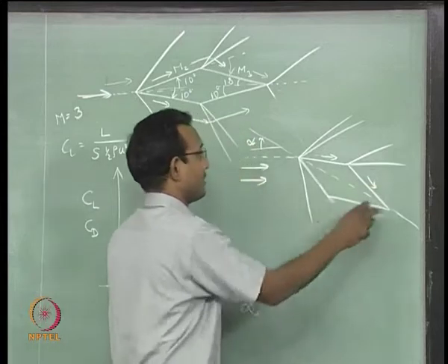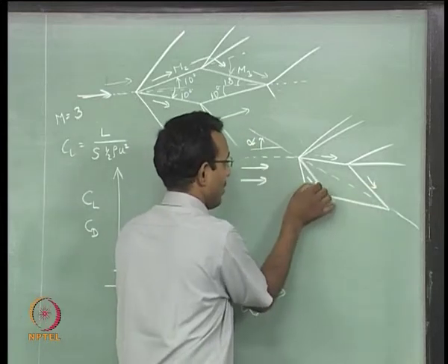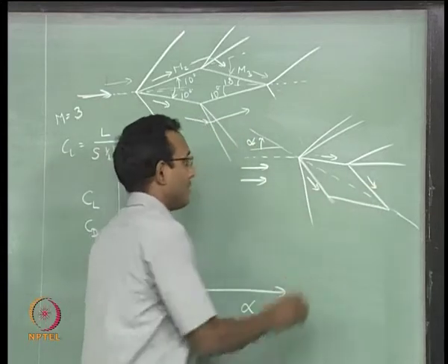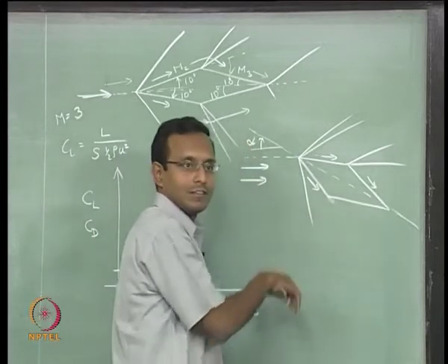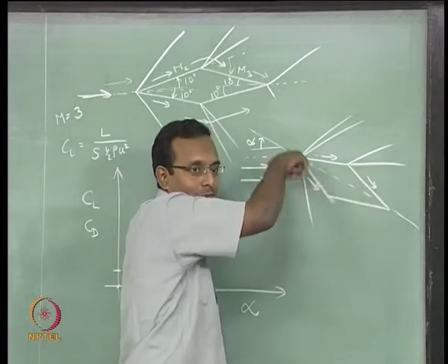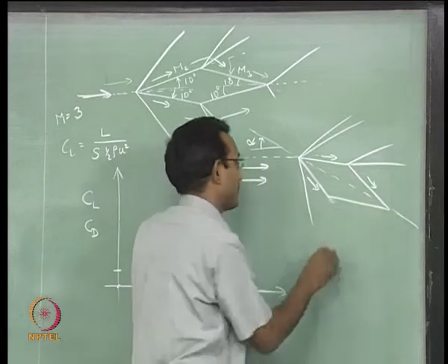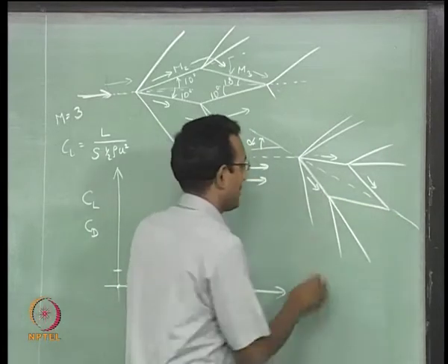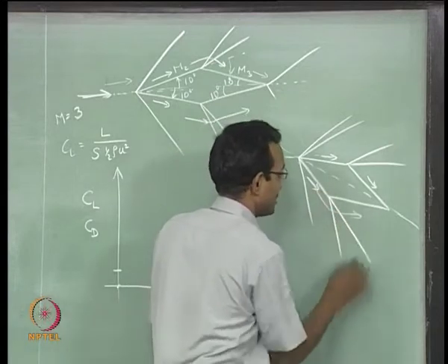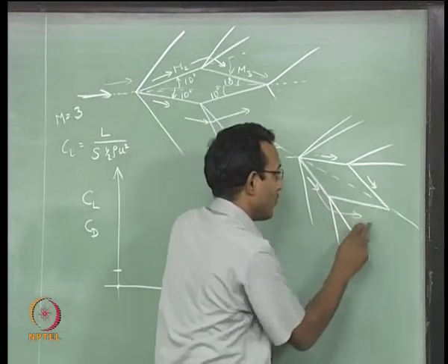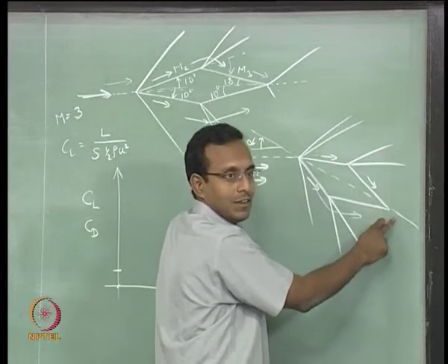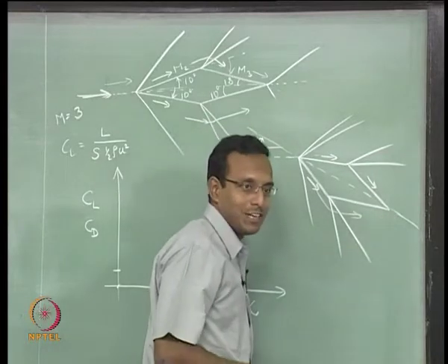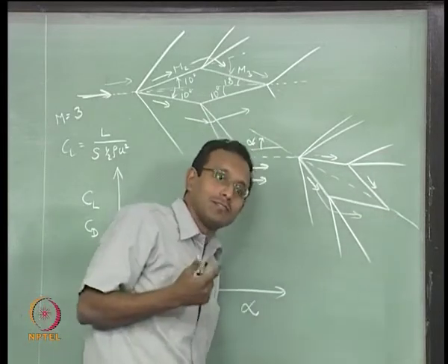Let us go on the bottom side. We have gone here, it is going along this. Now what will this see? Wall is going away from the flow, so it will be an expansion this way. Some expansion fan is going to turn from here to this direction. Now these two flows will meet, and I told you that the downwash is going to be really small.